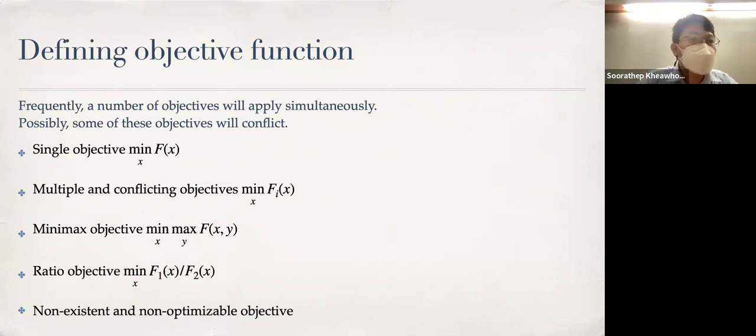But we need the control system because we have disturbance. So in a range of given disturbance or variability, we have to find the tuning parameter that minimizes the maximum error. The maximum error is determined by the disturbance or variability.